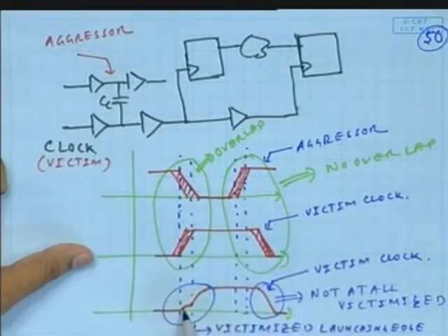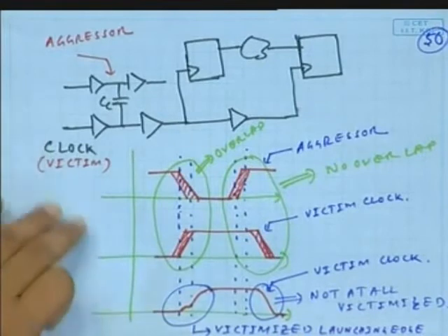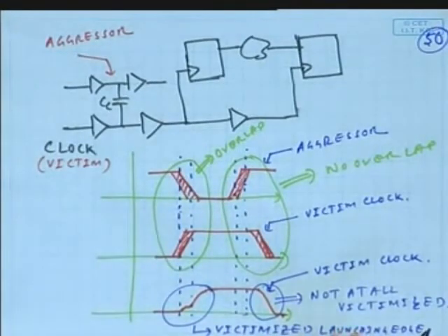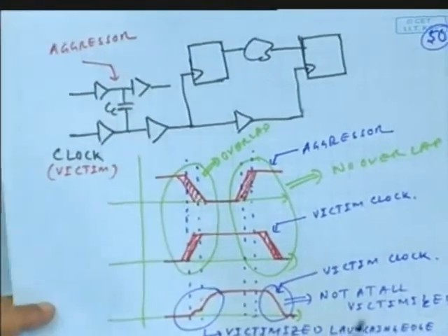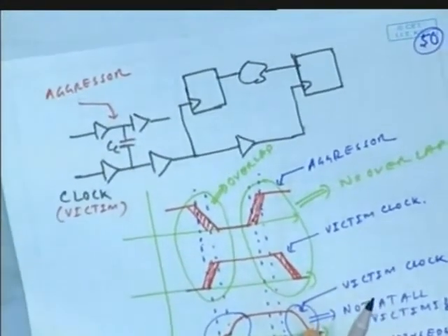So say for example, this one has become slower, that has no effect here because the window doesn't overlap at all. This is one example. This could be some other effect. So when you are doing the setup analysis with SI switched on, you have to have CRP on. I mean, you cannot remove it. Clear?